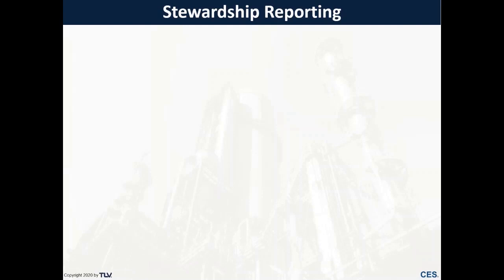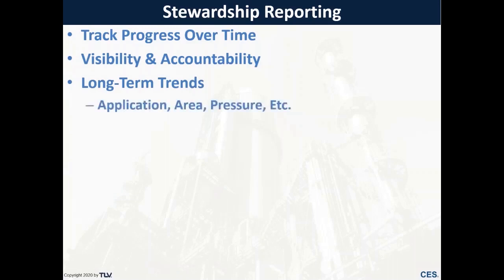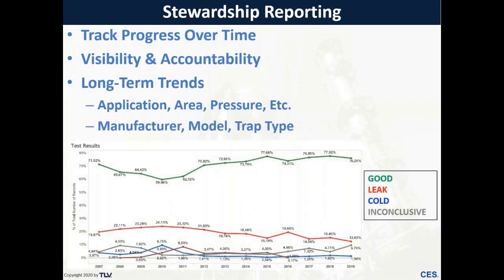So one of the key components to CDL management is what TLV likes to call stewardship reporting. And what this reporting does, it allows you to track your progress made for your CDLs over time, and it also provides accountability and visibility to the steam trap management program. And as you have that long-term progress in tracking that, you're able to see long-term trends such as what applications, areas, or pressures maybe are performing well, or maybe which applications you're having repeated failures with. You can also see what manufacturers, models, or trap types are operating best for your site.